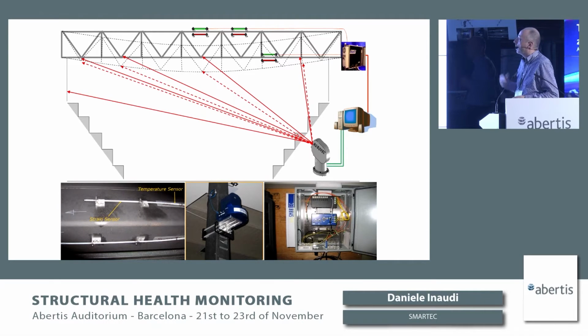So to address that, we have installed a network of fiber optic sensors that measure strain on some members that were selected as the most critical from the finite element analysis, and also a total station that would measure the deflections of the roof, so that we could correlate the strain with the deflection and with the snow load or concert load on the roof.